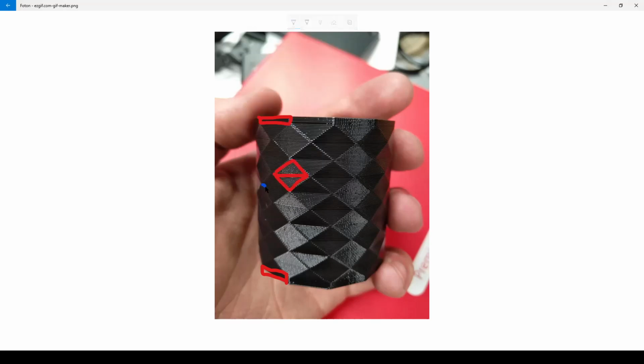If we have a look here, we can see here's an edge, here's an edge, here's an edge, here's an edge, and they need to be all the same length because we can see they are symmetrical, the same. So this should be the edge of a polygon. And then of course we see here the center of this edge of a polygon. Look up, we get a corner. So that means that this here should be the same polygon, only rotated by half the angular length. So this corner gets in the middle of this edge here. So that can be useful for the design.